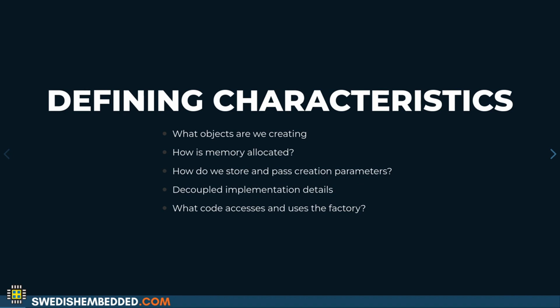And if we're coding in Zephyr, we would have the entry point to the initialization function placed in a specific section of the executable, and then a factory method that is part of Zephyr is going to execute all of the initialization methods, and those would be the actual construction method for each driver that is part of the system. But we're still creating those objects from a data definition of what needs to be created.